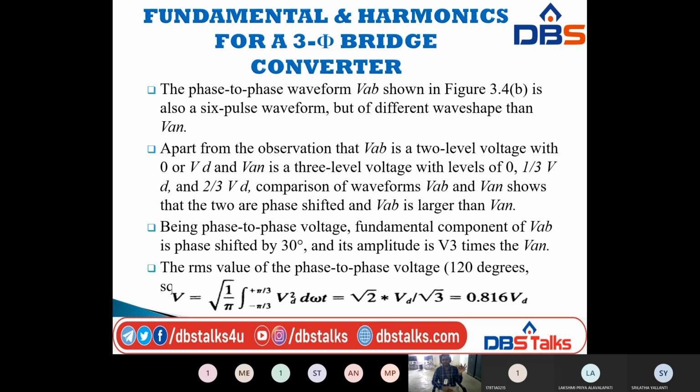The phase to phase voltage waveform VAB shown in the figure is also a 6 pulse waveform, but of different wave shape than VAN.